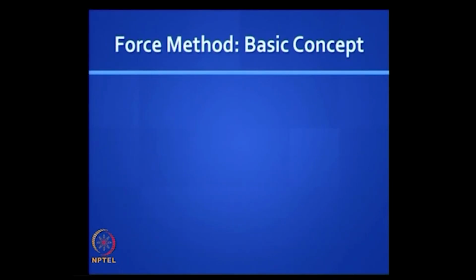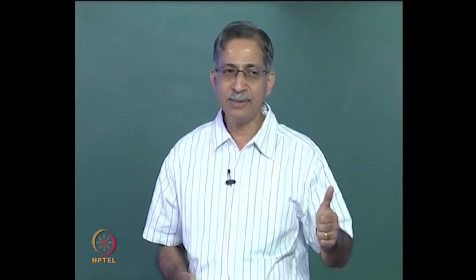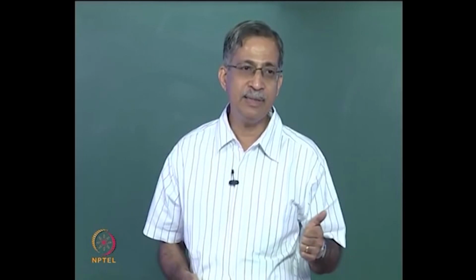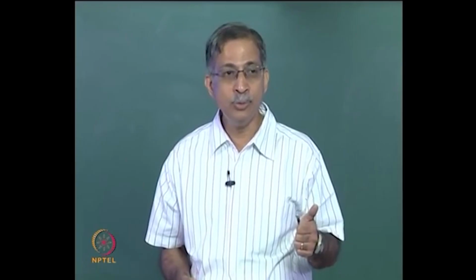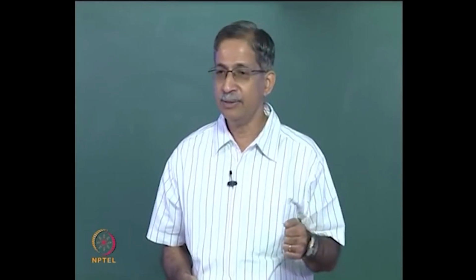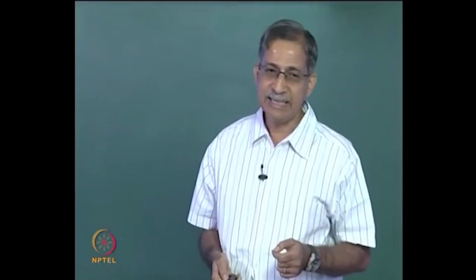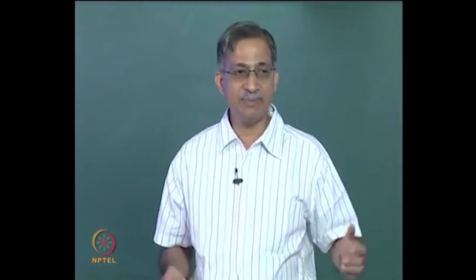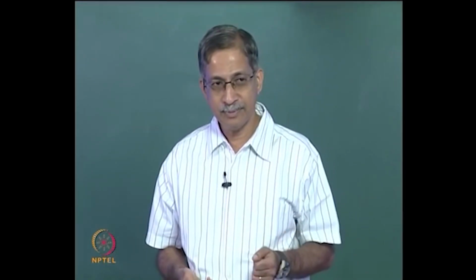Now let us summarize the basic concept underlying force method. What is the first thing you need to do in the force method? Identify the redundants, which also depends on the degree of static indeterminacy. So find the degree of static indeterminacy and choose, and you have choice here, choose your redundants. If there are n subscript s stands for static indeterminacy, then you have to choose as many redundants as the indeterminacy demands.